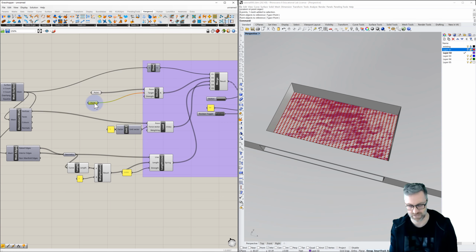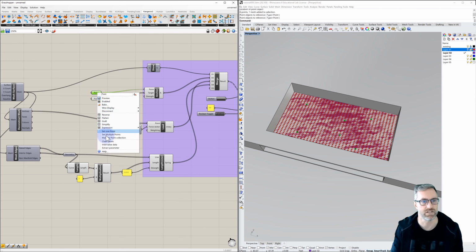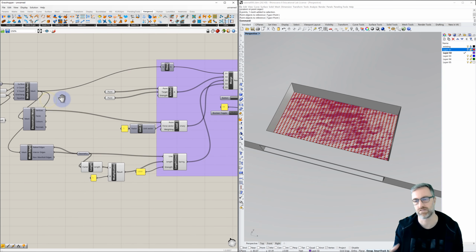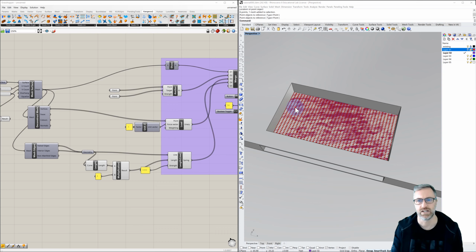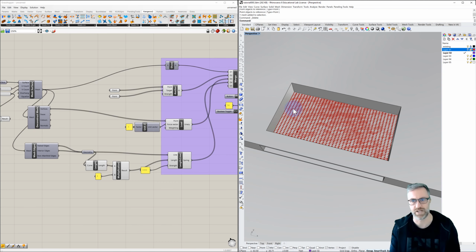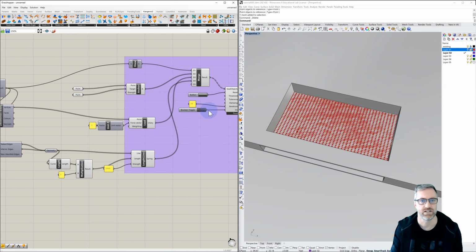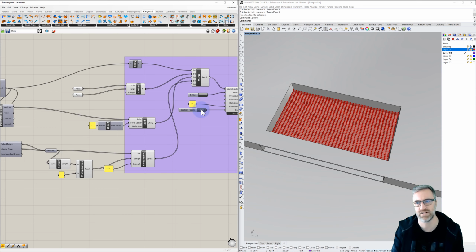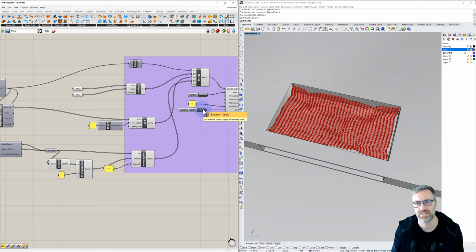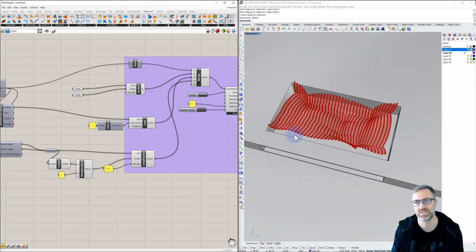And then I can even just delete the target points, copy the points, set them to the target. And then again, we just want to internalize the data, which basically breaks its reference from somewhere else so that those points now are no longer parametric. And I can even delete the baked mesh. Let's turn our solver back on. And now we're missing one of those points.